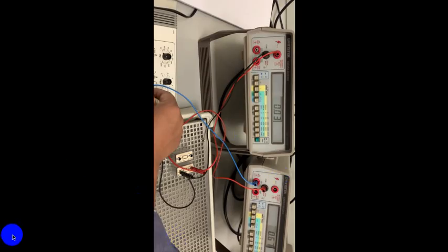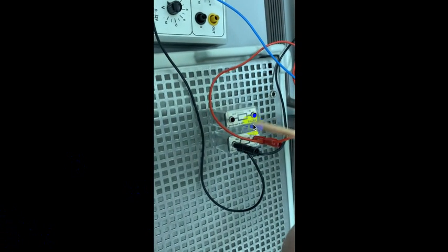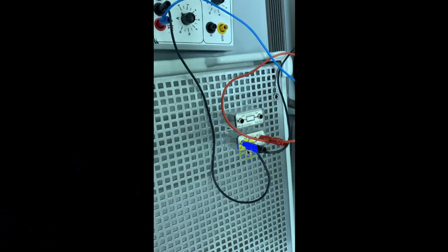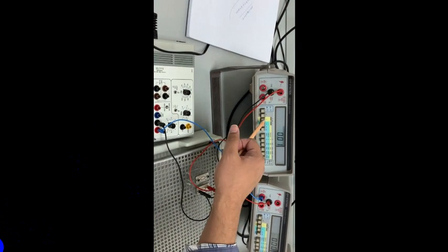Now accordingly we have changed the resistor from 1 kilo to 2.2 kilo. Okay, so just remove from here and connect it here. From here just make the connection like this. Okay, now approximately our resistor value is increased to 2.2, approximately double, suppose. Okay, now if I give 2 volt as an input voltage, so the current will be approximately 1, half, because now the resistor value is also increased, then current will decrease accordingly.